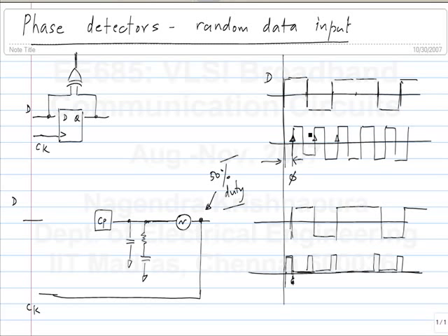No, actually, that is not a good thing because I take that back. The rising edge has to be in the middle of the data because, see, you want to delay the data, right? So that means that you have to detect the data correctly. To detect the data correctly, the rising edge has to be in the middle. So if it is near the edge, it will detect something near the zero crossing.